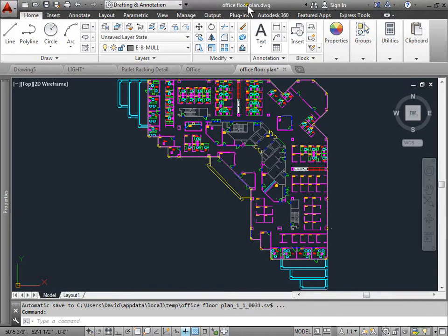Naming layers. You can create and name a layer for each functional category of objects and assign it properties to be common to the objects on that layer. By organizing objects onto several layers, you can control the visibility and the object properties of a large number of objects. And the way you name those layers can be controlled by a specific corporation, an industry, or even client standard. If you decide to organize your own layer scheme, choose the layer names very carefully.